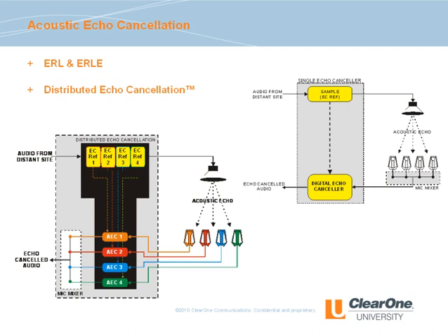Another major advantage has nothing to do with the echo canceller. ClearOne's distributed echo cancellation puts the echo canceller prior to the mic mixer. A function of the mic mixer is voice activation. Because the acoustic echo has already been removed, there is little or no chance that audio from the loudspeaker, the acoustic echo, can falsely activate a mic as it can in a single channel echo canceller, where the mic mixing functions have to occur prior to the echo canceller. All ClearOne audio conferencing products use distributed echo cancellation.